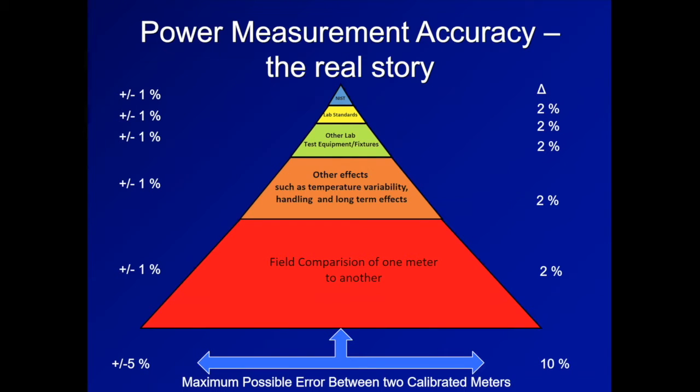Let's just analyze this very quickly. If you look at the things that you have to know about, you have to know with some degree of certainty what the thermometer temperature ranges are, in other words, what those uncertainties are. The purity of the liquid, the size of the channel, the rate at which it's passing through the channel. All of these things have tolerances and are subject to error. So that's one type of standard.